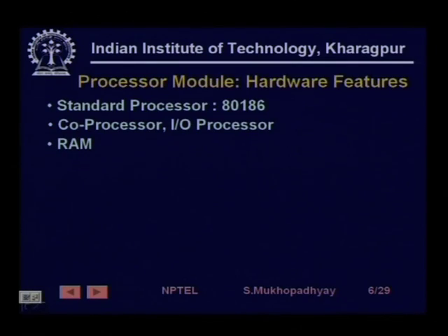You obviously require RAM for running it. Sometimes you have dual ported RAM. Dual ported RAM is RAM which has 2 ports, so it can be simultaneously written into and read from. This is important, especially when you want to read data from devices which are working, without stopping the device operation. You want to read data or write data. So, you can on the fly parameterize, dump some new parameters for a PLC while the PLC is working.